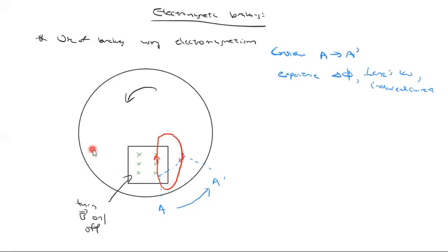You could also consider B to B prime. It doesn't matter too much, but if we consider the point B, which will then rotate to B prime, then it wasn't in the magnetic field, now it is. So it's gone from no flux to there is a flux. So it will try to counteract that into the page change. So it will create one out of the page. And with your right-hand grip rule, you'll be able to see that that will create on this side something like this.